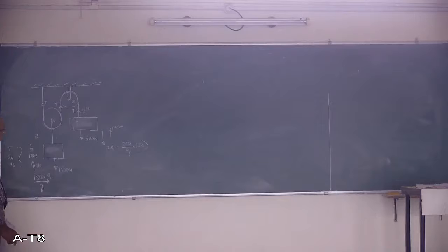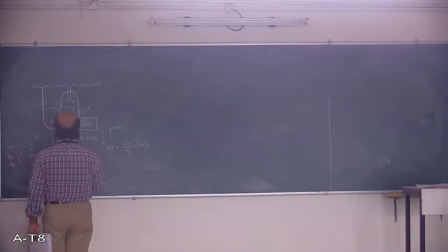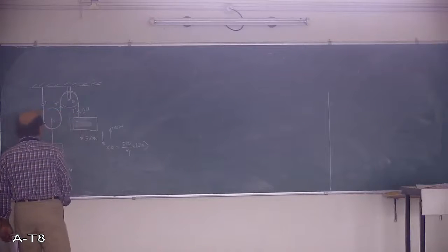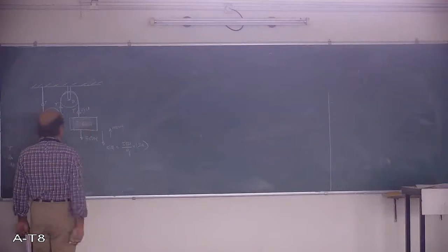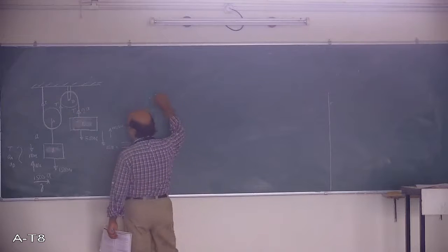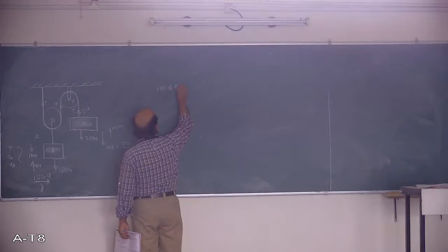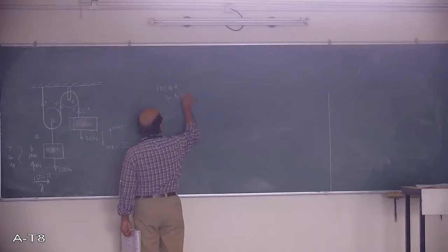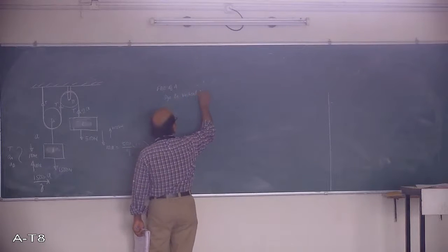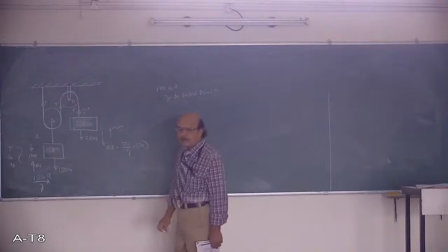Okay, these are the forces. Forces acting here will be 2T, here will be T. So these are the two, block A and block B. You can take independent forces on each block, this as A, this as B. Now I'll show you the free body diagram of A. So consider the free body diagram of A and apply dynamic equilibrium in the vertical direction.